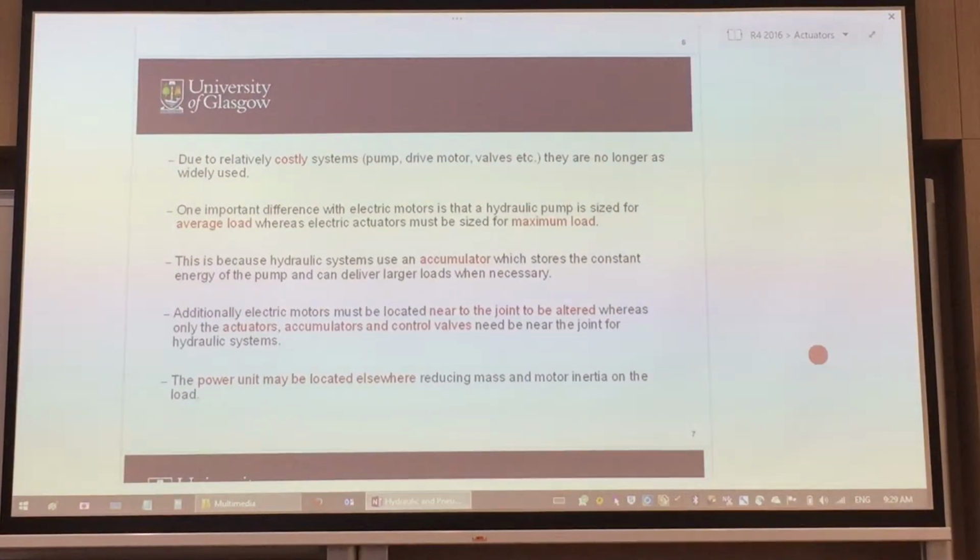If you talk to your chief engineer when you start working and suggest a hydraulic system, it may be rejected because it's costly. It's very expensive. Just because you need to set up a compressor, you need to have a hydraulic circuit. And the hydraulic circuit hose is actually not rubber hose. Rubber hose is cheap. It's actually metallic hose, because you need to withstand that amount of pressure.